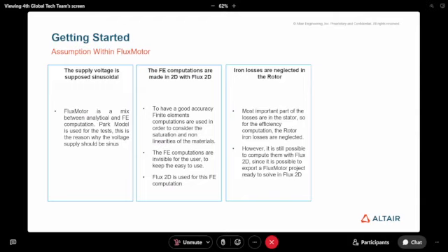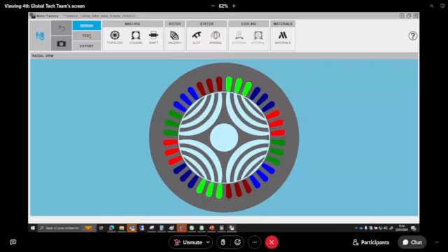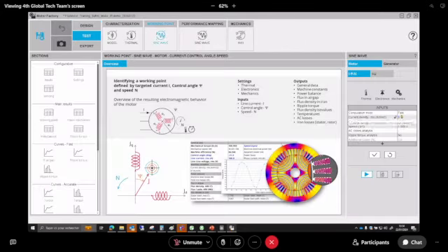Something also that we don't take into account directly in the efficiency map, for instance, the iron losses on the rotor are neglected. The joule losses on the magnets for the permanent magnet machine are neglected as well on the rotor. But there are some tests in Flux Motor. When you see, for instance, this test, there is FAST, which is using Park model and magnetostatic computation, and accurate. When you see accurate, it's the full Flux study, full finite element computation behind.